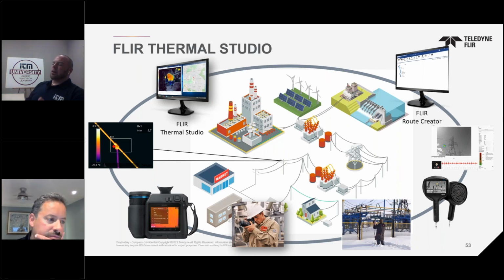What time of day would you recommend is the best to detect any water infiltration or heat loss on a rooftop? Very good question. During the day, especially in summertime, you get solar loading. There's something in thermal imaging called solar loading, which means the object under the sun is absorbing the energy of the sun, whether it's bricks, shingles, wood, or the gyprock of a wall. Remember, the sun is emitting a lot of heat energy, and that's being absorbed by the surface and actually stored until there's a differential.